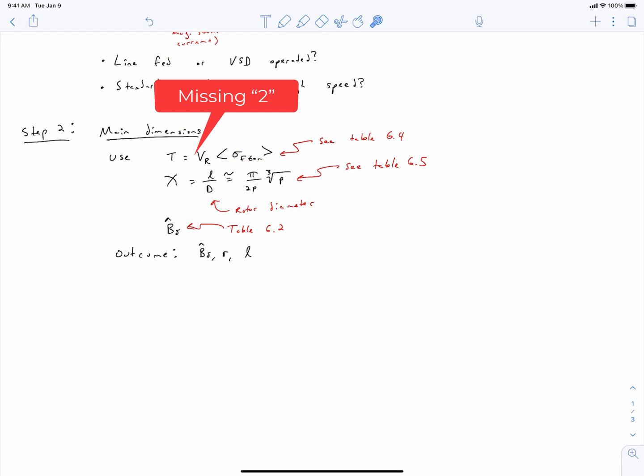Next, you need to figure out how to think about the volume of your rotor. And in our previous video, we talked about this in terms of a maximum surface speed or tip speed of our rotor when it's at rated speed. And that makes a lot of sense for high-speed motors or high-performance motors like a permanent magnet rotor with a carbon fiber retaining sleeve. However, oftentimes for induction motors, we're operating far below the maximum structural integrity of our rotor, and we have other reasons for picking a diameter or length of our rotor based more upon cooling requirements or a preferred aspect ratio.